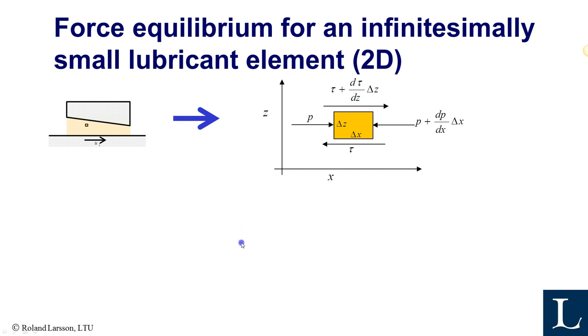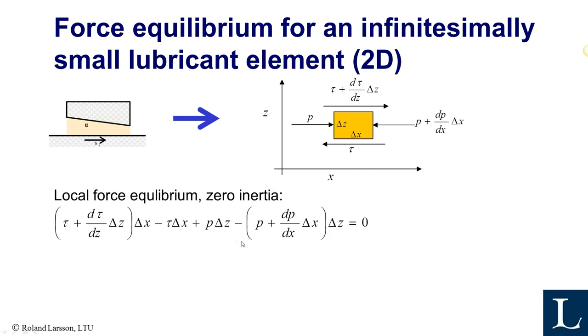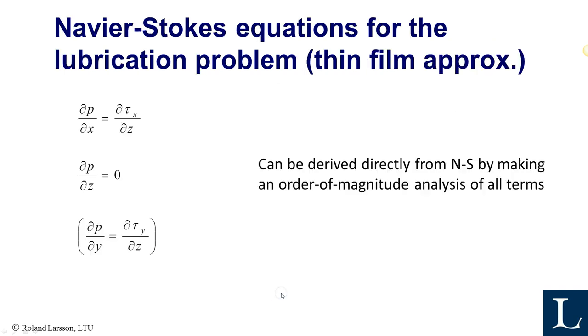If we apply the force equilibrium, assuming zero inertia and also stationary conditions, the equation looks like this. And if you simplify, this can be simplified to dτ/dz equals dp/dx. If you study this carefully, you may see that this is one of the Navier-Stokes equations for the lubrication problem.